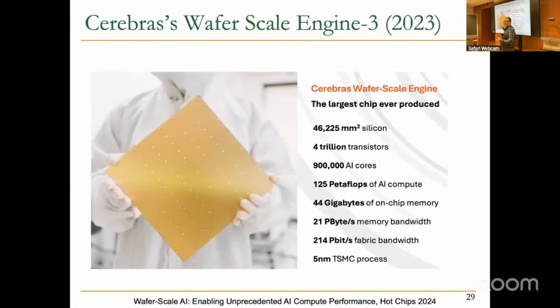This is your chip in Cerebras. For sure, you need a lot of power to power this up. But it's also quite efficient, in the sense that you lose a lot of power and efficiency when you go outside the chip because of packaging overhead. Here, because the dies are connected with thinner metals and thinner connections, you consume less power and you're much faster in your data movement.